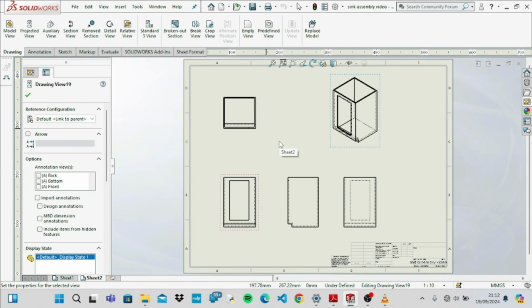You can add dimensions to a drawing, however, these are reference dimensions and are driven. You cannot edit the value of reference dimensions to change the model. The value of the reference dimension changes when the model dimensions also change.